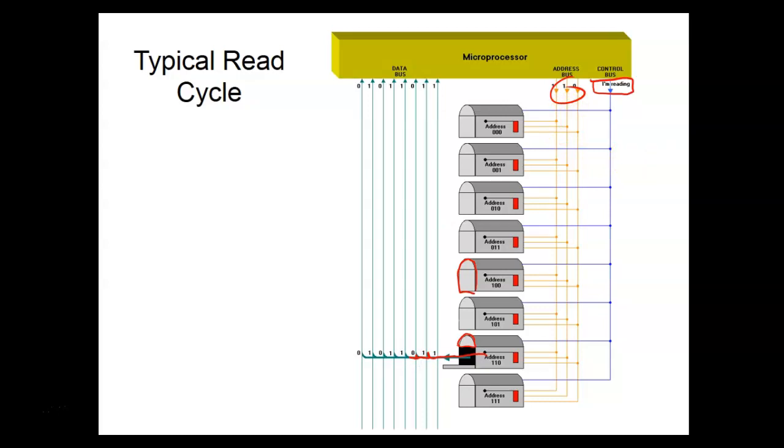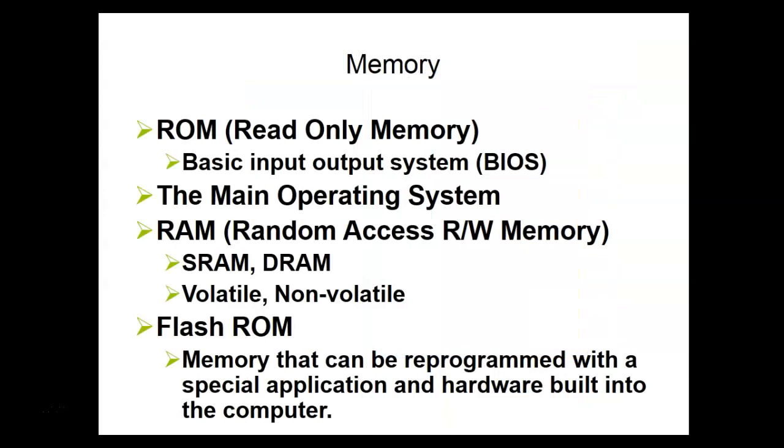So the bigger the address bus, the more things you can do what? You can select. The bigger the data bus, more information you can send during one read or write cycle. The bigger the control bus, the more control you have over that communication. So there's a lot of stuff on the control bus that if you take advanced microprocessors, we'll talk about interrupts and other things that's available to us that makes processing a lot simpler. We don't use interrupts in this class.